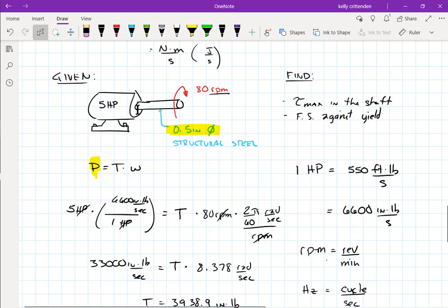Maybe you've got to spin the motor a lot slower and then gear it up later so that the output is actually 80 RPMs, but the motor's only spinning at like 5 RPMs or something. So maybe that would be one way to solve it. So next time, Monday, we'll talk about how you deal with the gear trains.